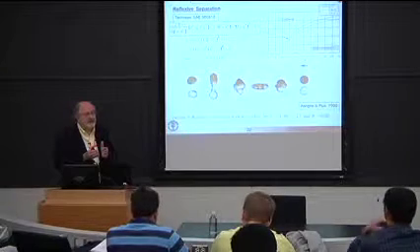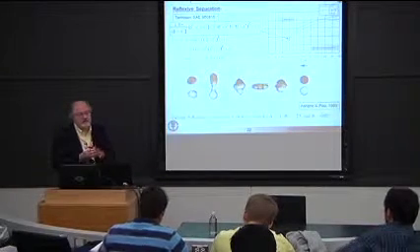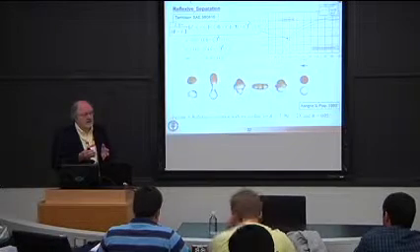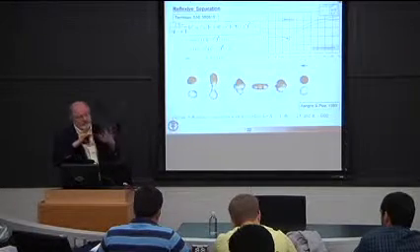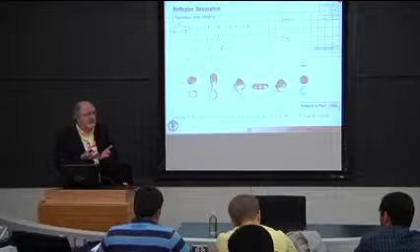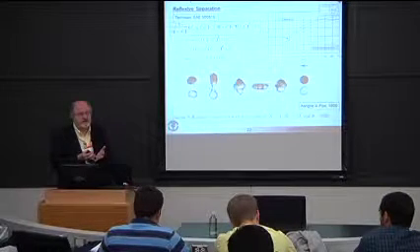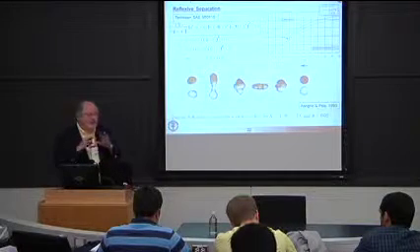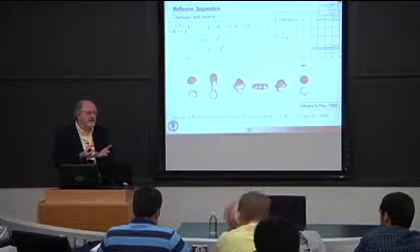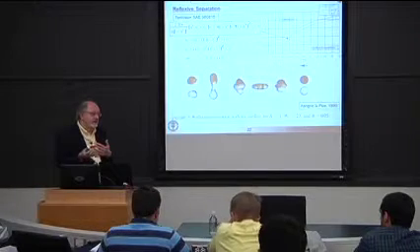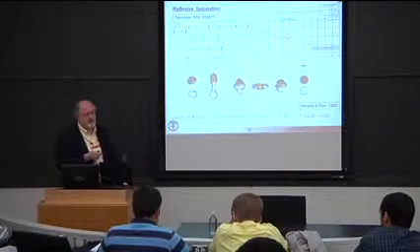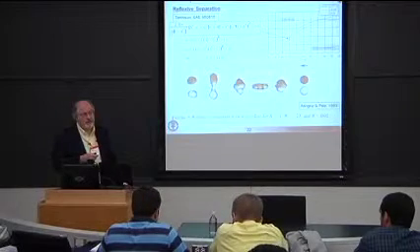So what we do now instead is we use what's called a radius of influence collision model, where we decide that we're going to take a group of cells, but we're always going to use the same radius of influence. Typically, it's on the order of several millimeters. And then look at all the drops inside that radius of influence, check whether they can collide using this stochastic idea, and then the outcome of the collisions is calculated.